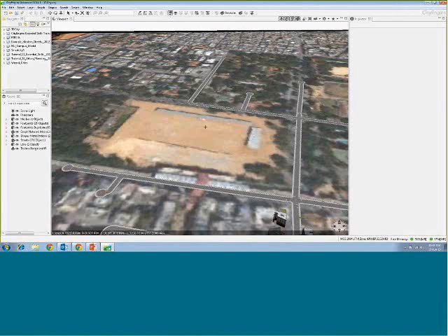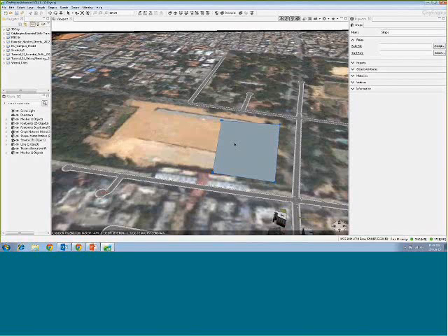This one is just to demonstrate that if I am trying to create these plots on my own, they can manually model this into a 3D model, or they may use a ready-made tool, or they may use various rule samples provided to actually transform themselves into a more 3D manner. If you could see any of the wizard city rules, I just need to drag and drop a rule on top of my plot. The moment it is done, it would ask you for the type of alignment. So I may align it as an open space, and I may model trees or I may not.